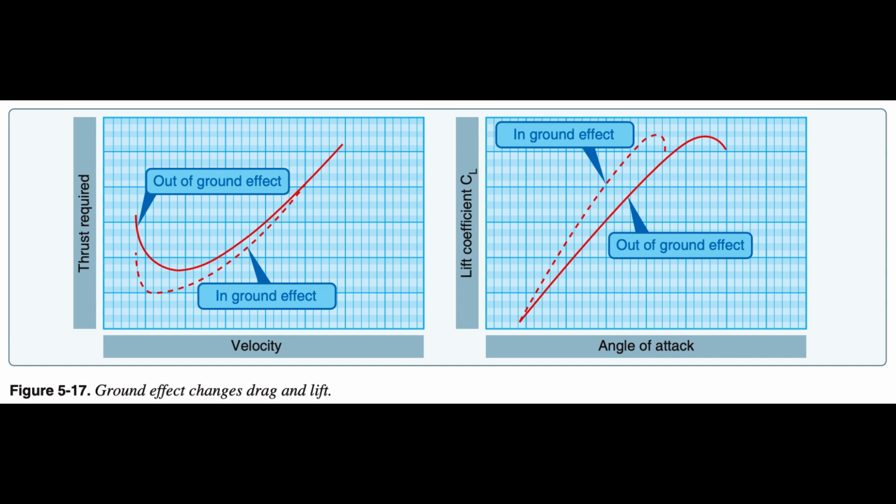In order for ground effect to be of significant magnitude, the wing must be quite close to the ground. One of the direct results of ground effect is the variation of induced drag with wing height above the ground at a constant CL. When the wing is at a height equal to its span, the reduction in induced drag is only 1.4%. However, when the wing is at a height equal to 1/4 its span, the reduction in induced drag is 23.5%, and, when the wing is at a height equal to 1/10 its span, the reduction in induced drag is 47.6%. Thus, a large reduction in induced drag takes place only when the wing is very close to the ground. Because of this variation, ground effect is most usually recognized during the liftoff or takeoff or just prior to touchdown when landing.